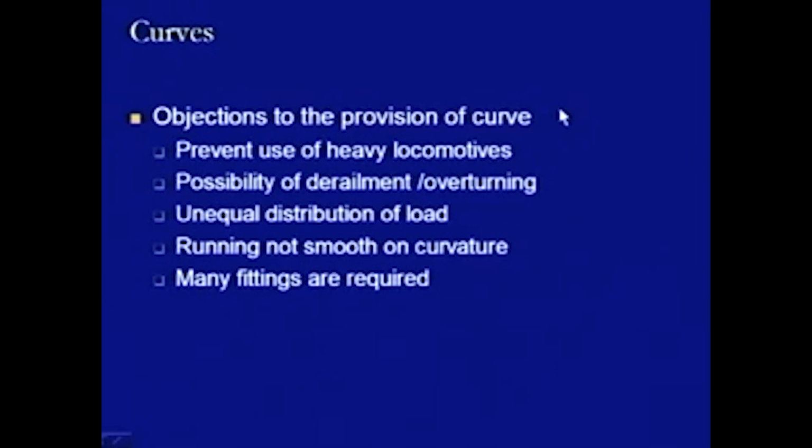As far as the horizontal or straight section is concerned, the two things which are happening are the longitudinal movement, and at some point of time a lateral sway or oscillation taking place. But when we come to the curved condition, then there are some more forces which will be working along with the same forces which work on the straight section, and those forces are the curve resistance and the centrifugal force.